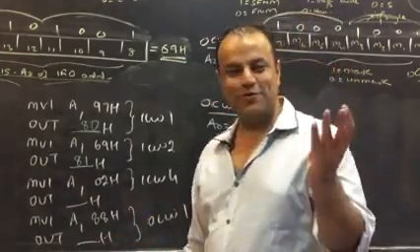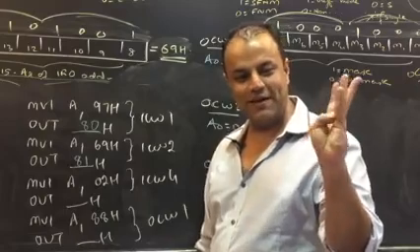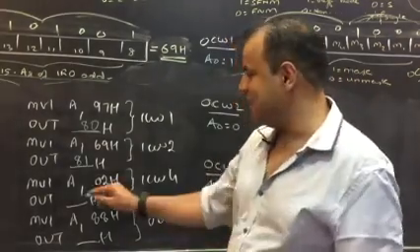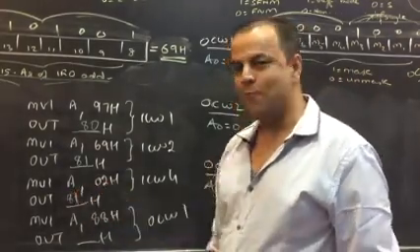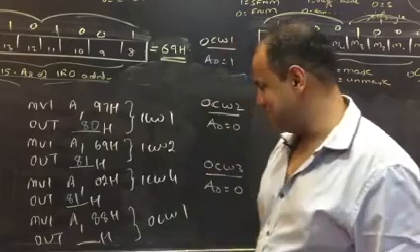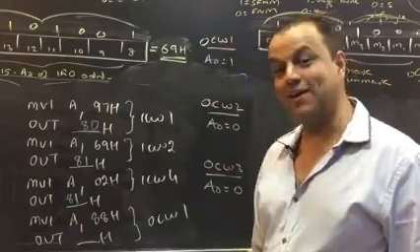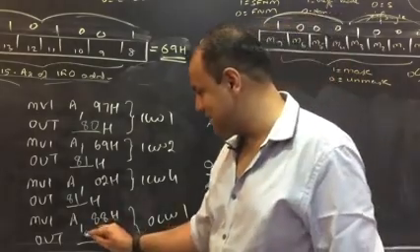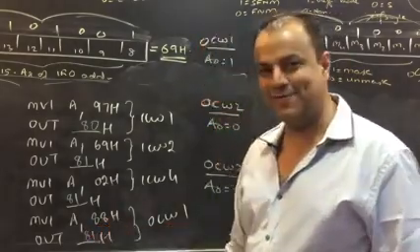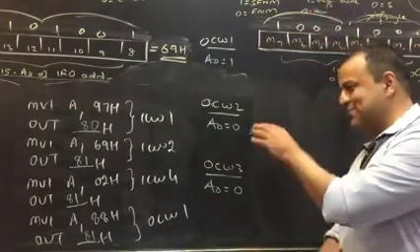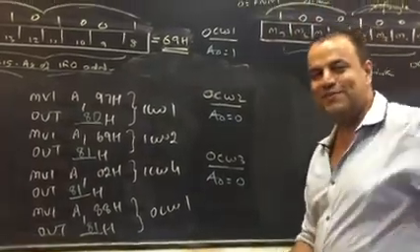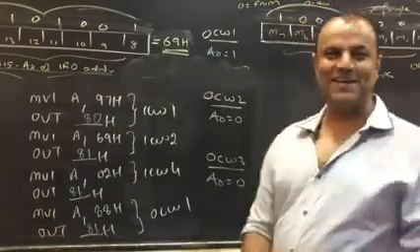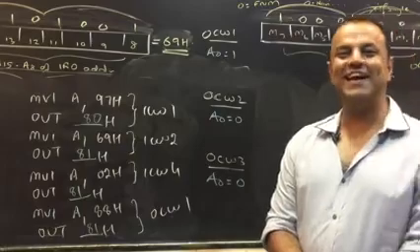You will give ICW4. Now come on, properly. ICW1 we give at 80, ICW2 we give at 81. There is no ICW3. You will be giving ICW4 at the address 81. Yes, 81. You will give OCW1. Now properly. OCW1 you will give at the address 81. If there was an OCW2 to be given, you would give that at the address 80. If there was an OCW3 to be given, you would be giving it at the address 80.